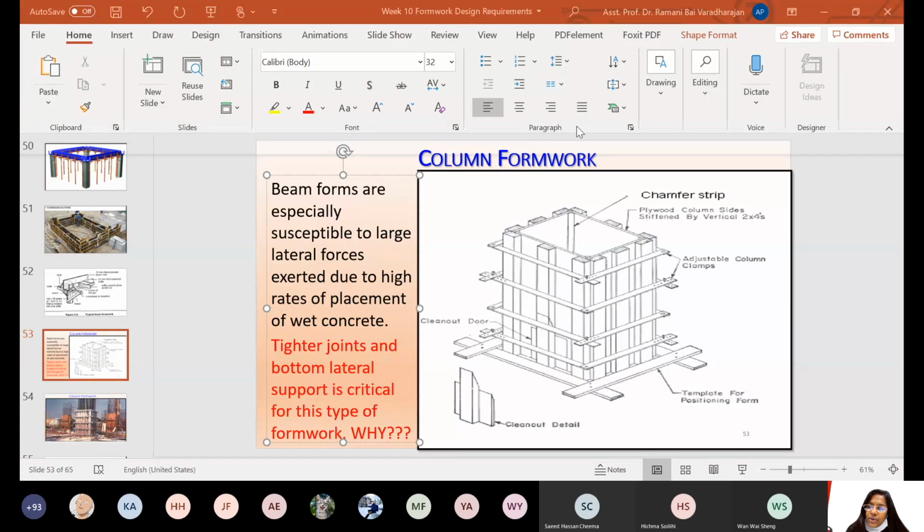So in doing so, you have to take care of the joints. You finish one part, and the next part when it comes, you have to properly connect them together. That's why they leave an uneven surface and then they join by next parcel. So the difficulty is maintaining the proper joints, or how you close these joints, how you continue with the beam work, which is extending in a length direction.